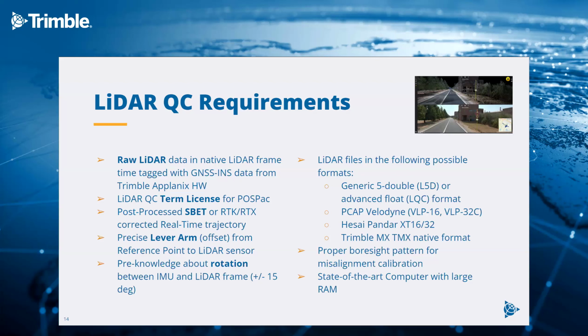LiDAR files themselves are available in the following formats. We have our own internal formats, or let's say we have two. One is called the generic 5-double format, and we also have an advanced float format, which we call the LQC format. Users integrating a LiDAR would typically need to convert the native format into one of these formats to make it readable by LiDAR QC.